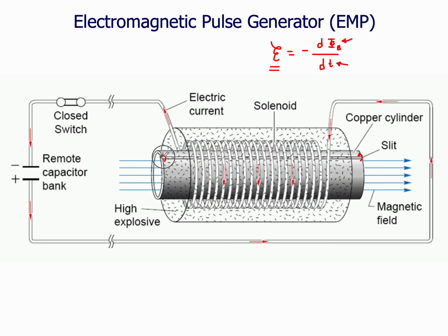That kind of electric field produced by this very high voltage over the short distance, remember again, electric field can be written as the change in voltage over the change in distance, is going to create this incredible field which is going to spread out from this device in all directions. When that interacts with electronic devices, it's going to induce a large voltage.